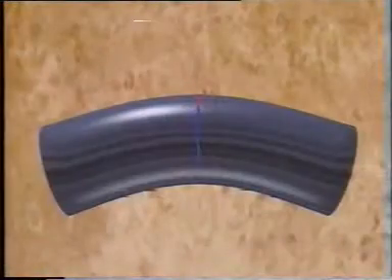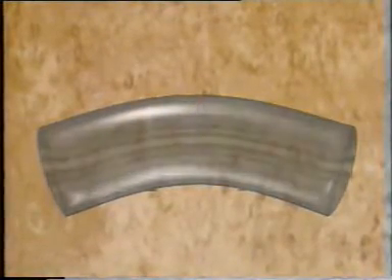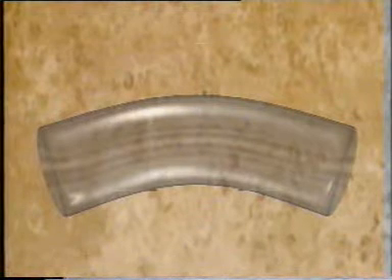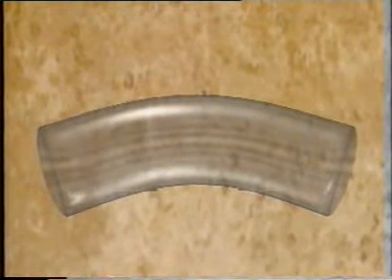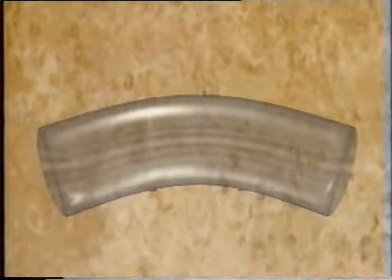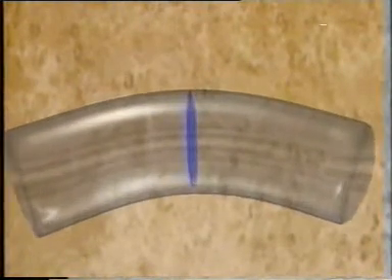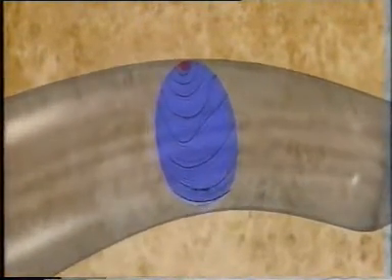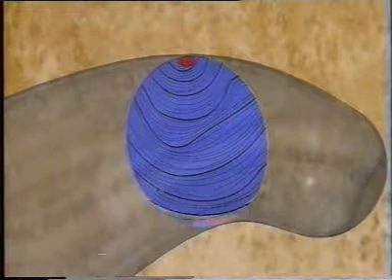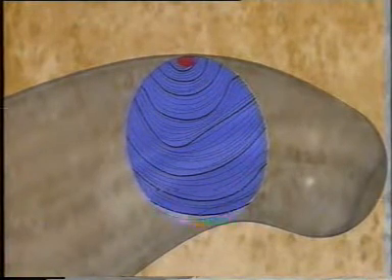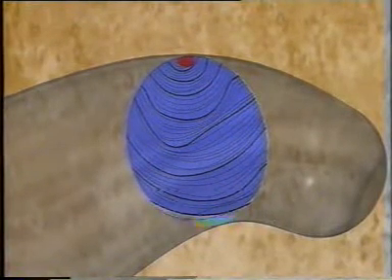On the microscopic scale, the most important feature of the fatigue process is the nucleation of one or more cracks under the influence of reversed stresses that exceed the flow stress. Subsequently, fatigue cracks propagate by a series of opening and closing motions at the tip of the crack, producing the striations which form within the grains. The cracks initiate at points of maximum local stress.